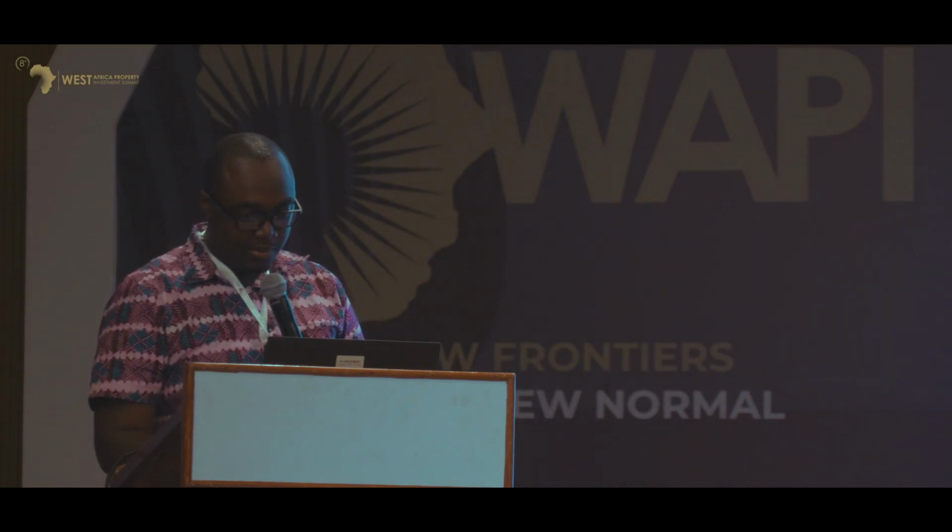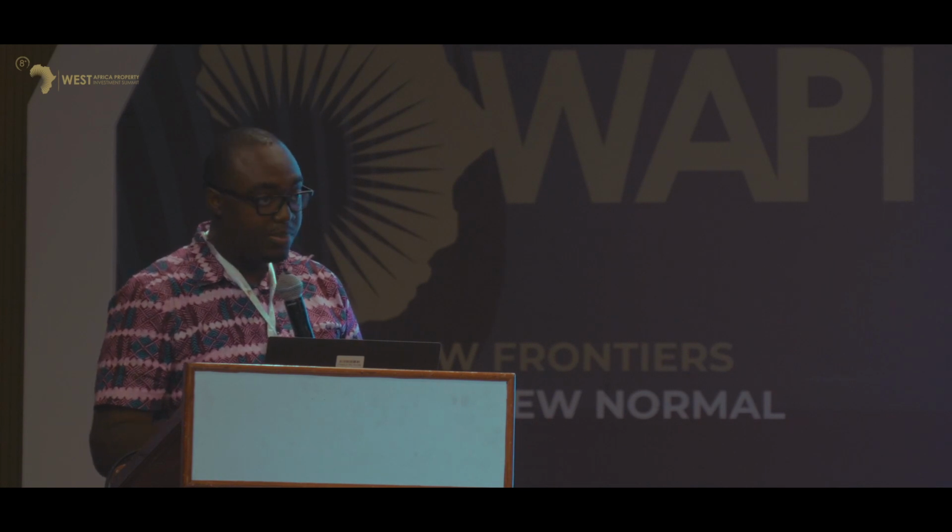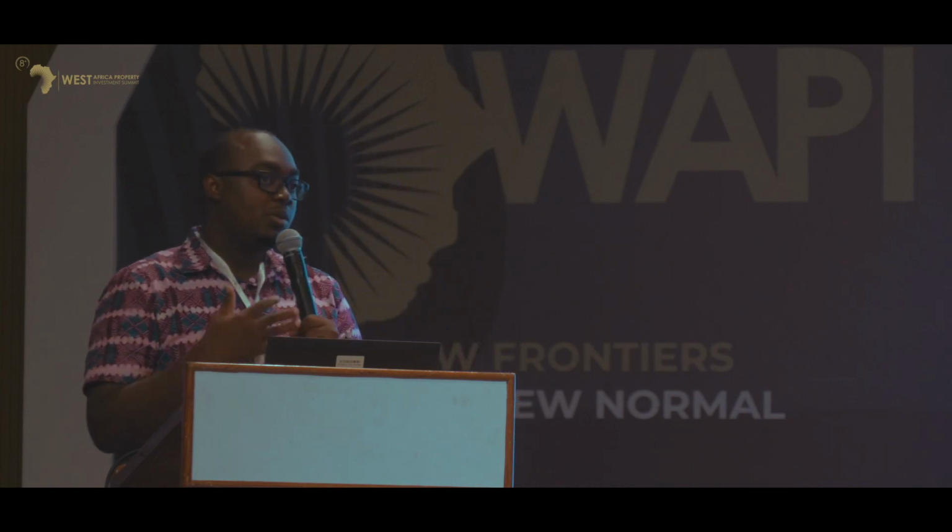Some of the measures we want to implement in the building are around the window to wall ratio. Very critical when designing buildings is to look at what's the dimension of my windows to my walls. Why? Because we want to look at the heat gain into the spaces, and depending on our climate, how we are able to reduce the heat gain, which ultimately impacts the energy use in the building.